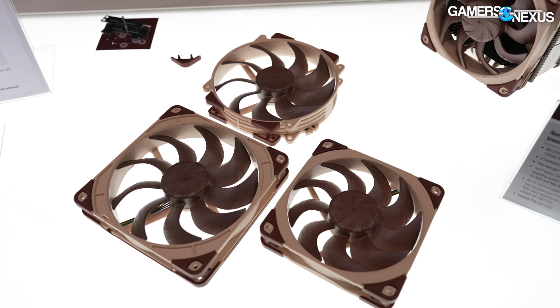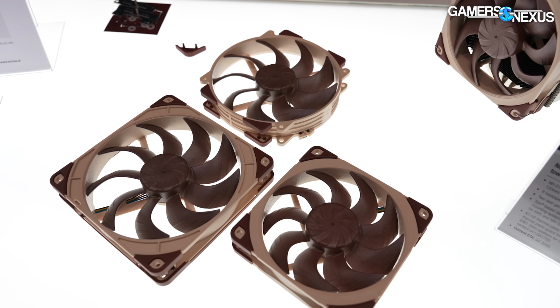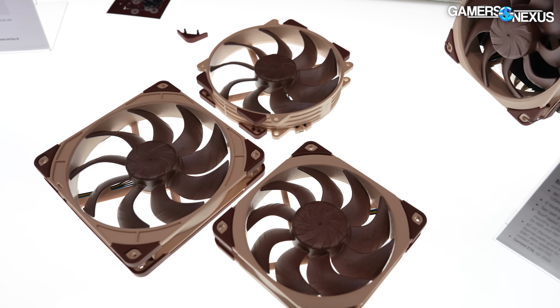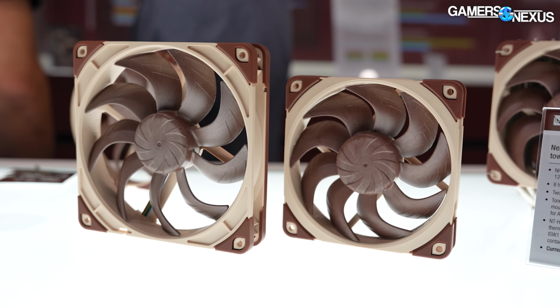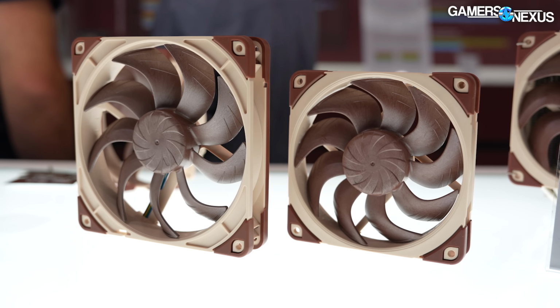So for our space, I would say 120 millimeter fans, we're talking now, I would say 9 blades is the sweet spot. Especially if you want to go for good static pressure performance or good performance against high flow impedance. It seems like any company, when you've produced something you think is the peak of what we've done at this point, it seems like 9 blades is the sweet spot.